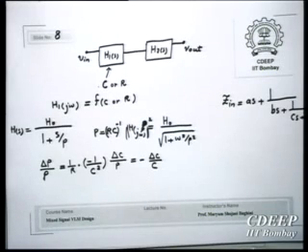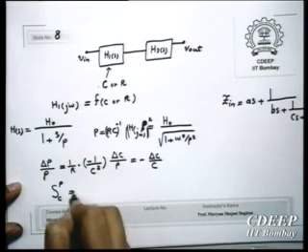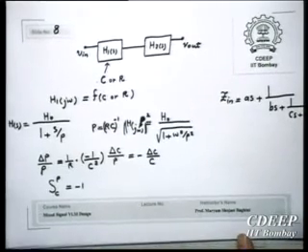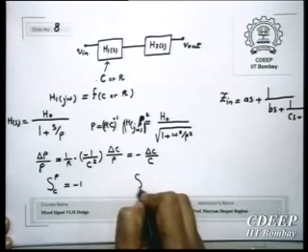For example, if we make the pole a function of a parameter that we want to look at, the sensitivity of P to C is equal to minus 1. This means that if we have a 20% change in the value of the capacitor, the pole will change by 20%. And usually if we have an LC ladder filter with very small ripple in the passband, meaning rho is almost close to 0, it can be shown that this sensitivity is actually less than 1.